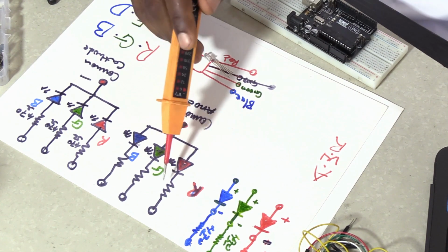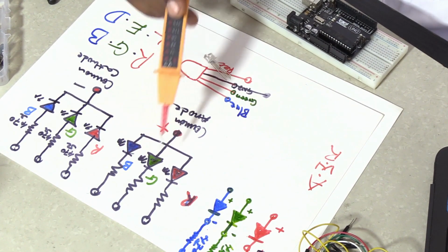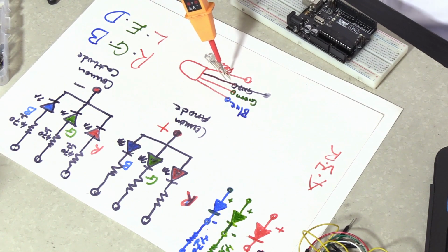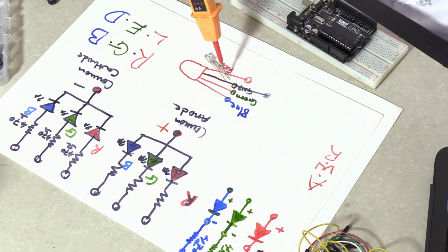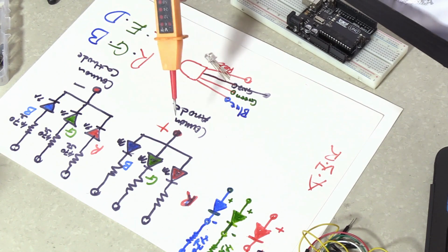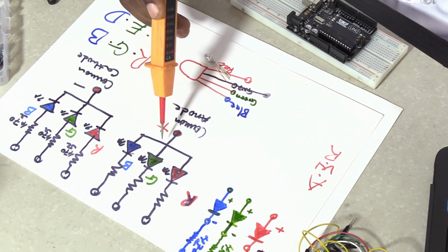Now you link 470 ohm resistors in series with these legs, except the ground, which is the cathode. Some of you will like to put one resistor on the cathode, and the current will be looped up through that resistor. I don't think it's a very good idea. So you better link up all the three legs and put resistors there. That will be a better option for you.